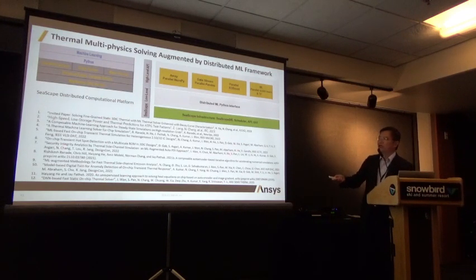We also published quite a few papers, and also an upcoming ICCAD paper, to solve the problem of how, when we apply the ML solver, we go down to 10 micron by 10 micron. Because the ML solver is comfortable with the 200 micron mesh grid, but cannot solve 10 micron by 10 micron. And how do we extend that application to handle 3D IC in terms of the vertical thermal coupling? That's another question that we need to solve.